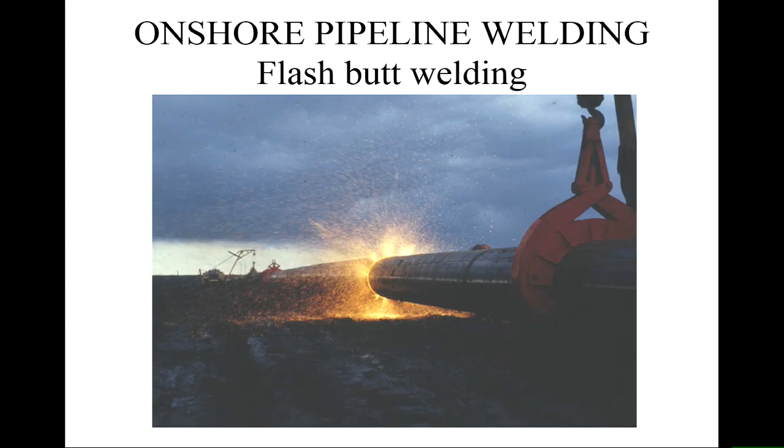That's it happening on site. So you can see the same sort of thing. You see all these arcs here. You can see these ones are slightly more intense there. So if there's contamination and there's bits and pieces on the surface which are different, you can sometimes get non-uniform arcs, non-uniform heating. You have to control the edge preparation quite well because of that. You've got these very big clamps lifting things up, and there are insulators in the clamps to stop the power dumping its way through the supports. You'd kill people if you did that, so you need to have very good safety control.